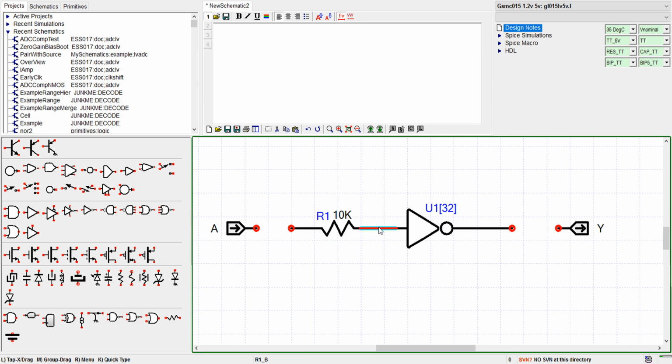So what I'm going to do here is set up a little test again, and I'm going to add here a 250k resistor so that the noise is really bad. The jitter for this chain of 32 inverters is worse than it would be due to the presence of that extra resistor. So I think you can possibly see what I'm doing here. I'm doing the same trick as before.